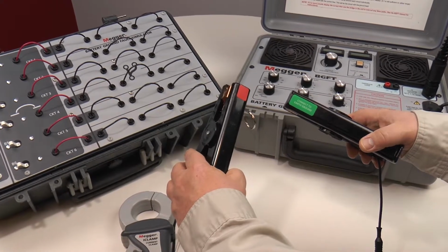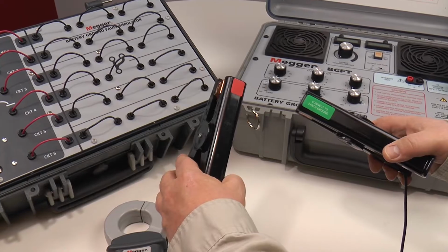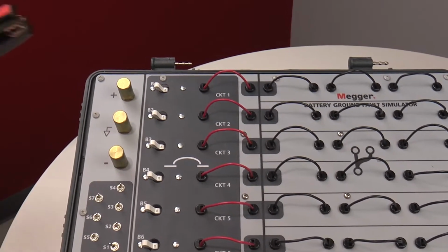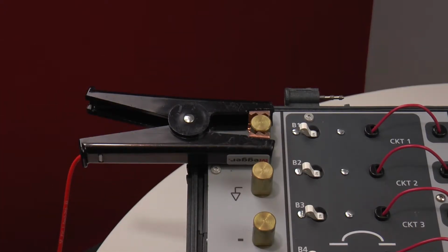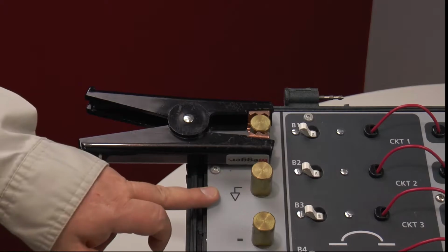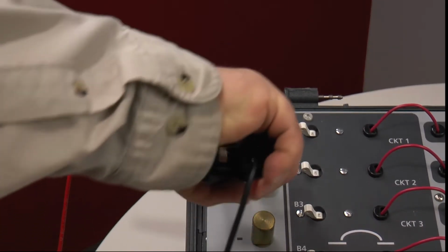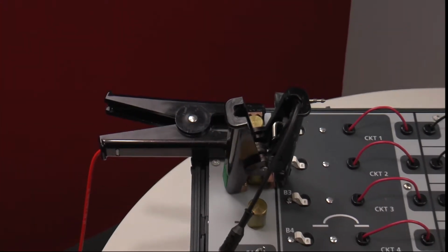Connect the transmitter's leads to the transmitter. Connect the transmitter's leads to the battery string. Since this is a positive fault, connect the transmitter lead with the red label to the positive side of the battery string, and the transmitter lead with the green label to earth. Never connect the transmitter leads across the battery string. You could blow the fuses.